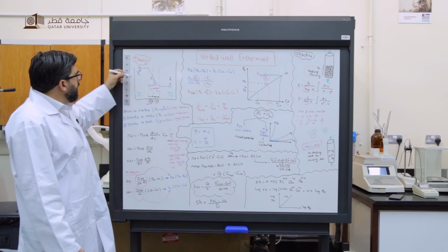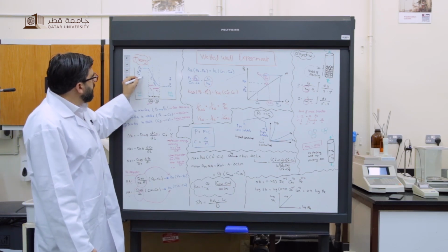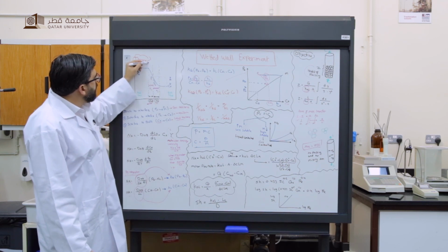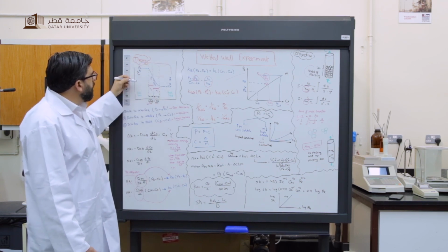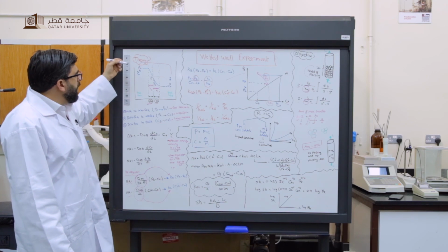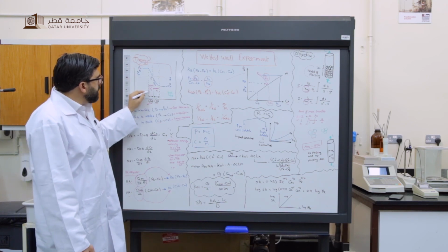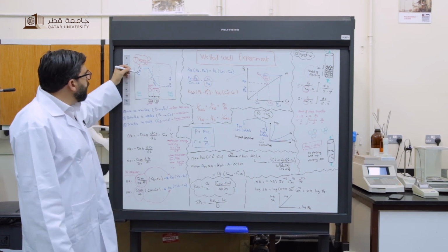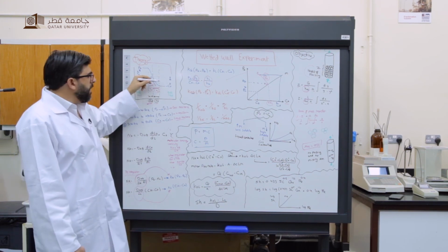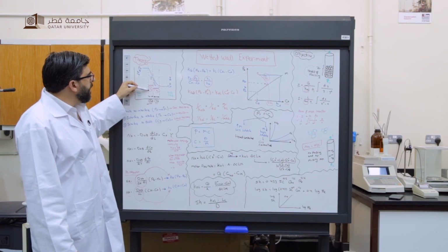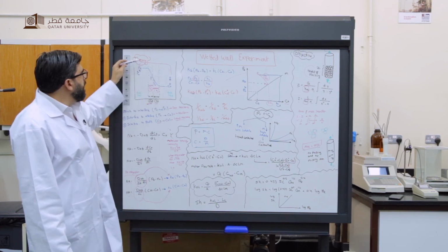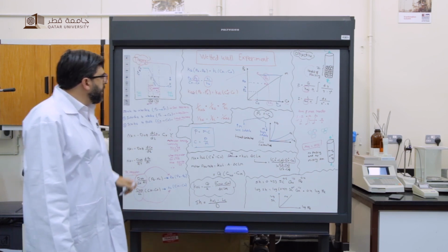Now for overall, start from C star to CA and from PA to P star. So the individual mass transfer is involved inside both. That means KOG includes both KG individual of gas phase and individual of liquid phase, and the same thing for the KOL, also vice versa.